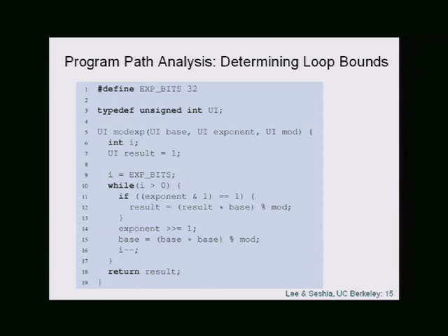Again, for embedded code, since you can't really prove program termination in general, you have to follow fairly strict rules. And in this case, the rule we're following is that the loop counter gets decremented once every iteration, for sure, because any path through this loop has to decrement I. So if you make sure that you have that kind of pattern in your code, then this loop will terminate.